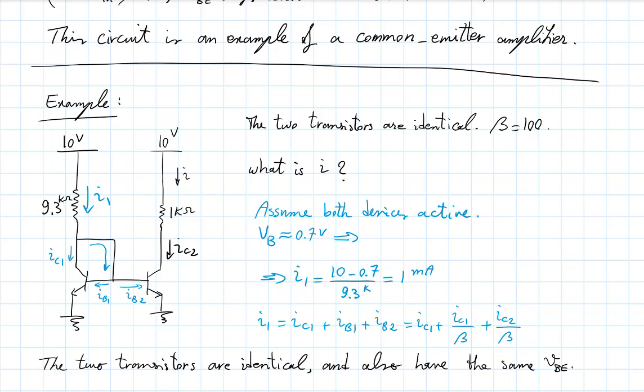So far, we've talked about voltage sources, how you actually make a real voltage source. We talked about that, DC voltage sources, using diodes and all that. This is a current source. How would things change if I change the 1 kilo ohm resistor to 2 kilo ohms? Nothing. Regardless of the voltage variations in this collector branch of the second transistor, the current in this would not change. So you have something that you can connect different values of resistors to, and it would drive the same current through them. And that current is determined by the other side of the circuit.